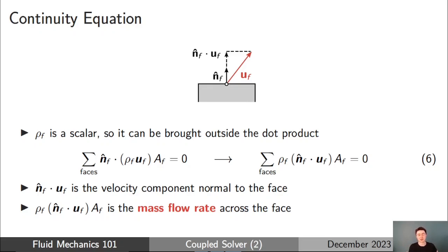Because what I've done so far are quite a few mathematical tricks and mathematical techniques, but when we write it in this form, this allows us to regain a lot of the understanding of what we've actually done here. And the key to that understanding is to look at the terms closely, and if we start in the middle, we can see we've got the dot product of the unit normal vector and the velocity at the face center. So if we think of a general cell and a general mesh, and we think about the face center, we've got a velocity vector there.